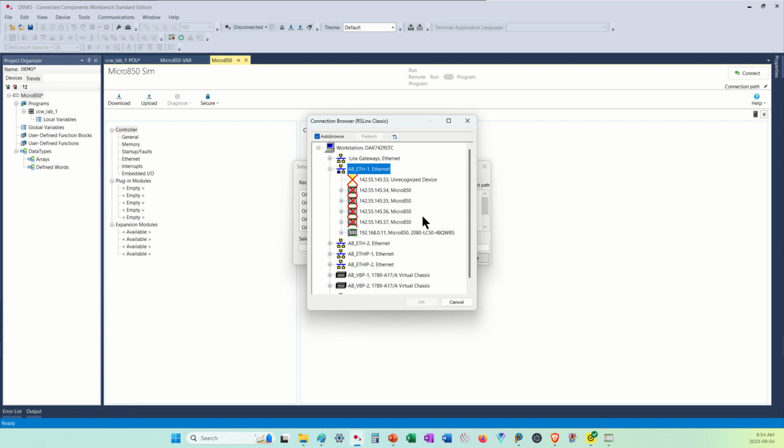They used to have what they called electronic data sheets. It was a small file that you would add to the project. And once it had that, it would know all the handshaking, all the communications, how much memory was going to be involved, how much I/O was involved, all the pertinent details about that particular device was then loaded into the project. And also there was an icon file that would look like the device that they wanted to, and it would then appear in this browser.